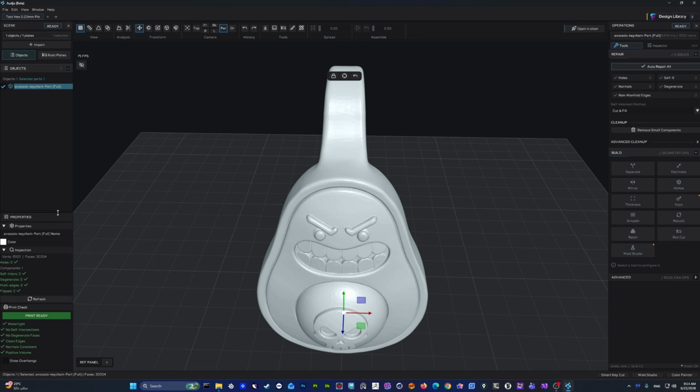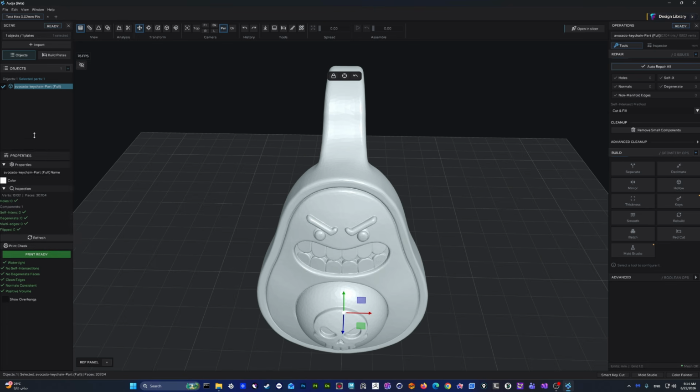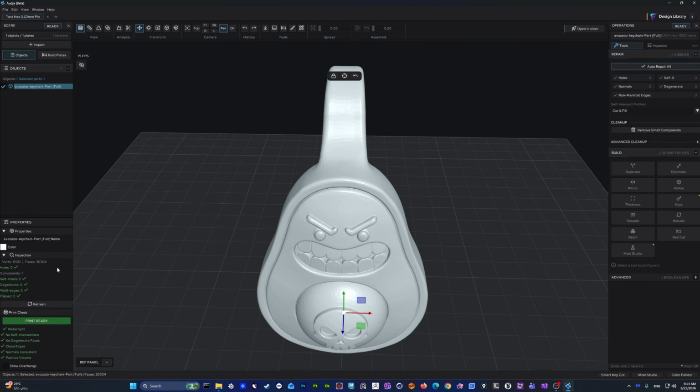And we have here the inspection section. You can control the height of it. It is showing the issues that appear here, but also the volume, and that's so important. It's saying if the mesh is actually going to be printed or will have more issues in boolean issues, because if the model or the mesh has issues in positive volume, you cannot do boolean even if your self intersections are solved. If there is any issue in your model, it's going to be orange color, and any of this is going to be orange stuff.